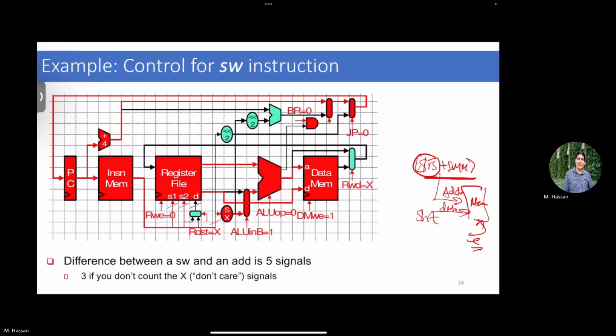Yeah, Arjun. Yeah, well, if you are really not taking that branch path and you are disabling it, no matter what happens here, you don't really worry about it, right? It doesn't need a control because the mux gates it, exactly, right? So it's only being used if it's a branch. And if it's a branch, you are 100% sure that this path is sending valid data to the ALU, which means if this is always adding, it's fine. Okay. Other questions? Good.